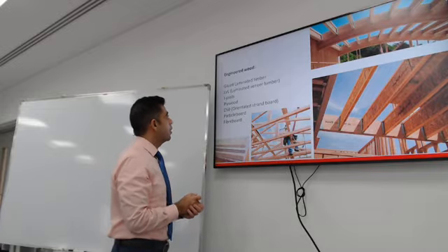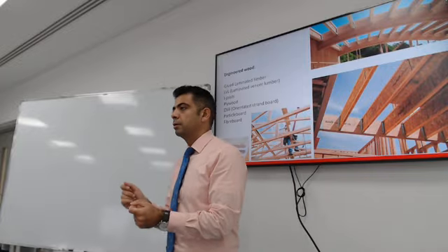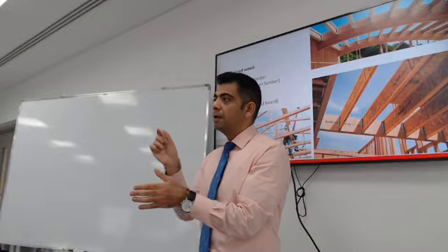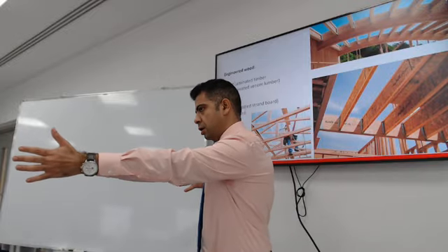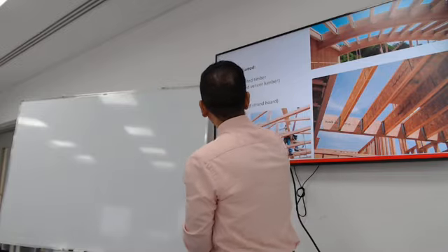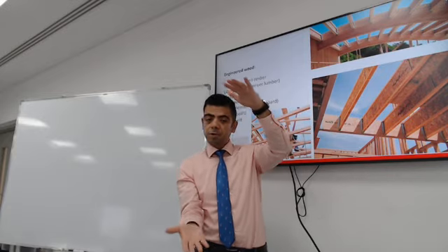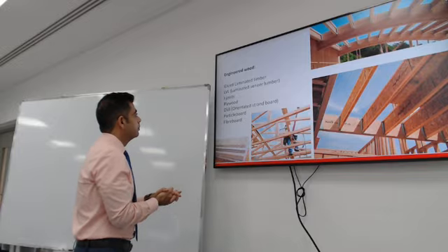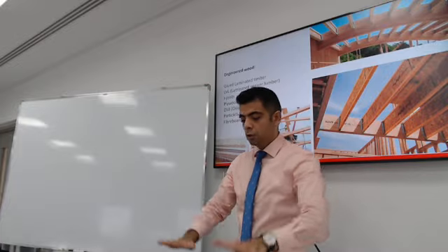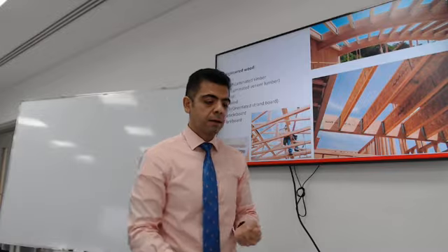Okay, another one is called the LVL, or Laminated Veneer Lumber. You can create beams out of it, you can create different products out of it. It's thin layers, and you can create a beam, or a bigger size, and you glue it together. The Glulam would look something like this beam. You know this arched beam? You can create curves, it's much deeper. Plywood, you can create sheets to cover up walls, or even floors or roofs, with, again, layers of wood.